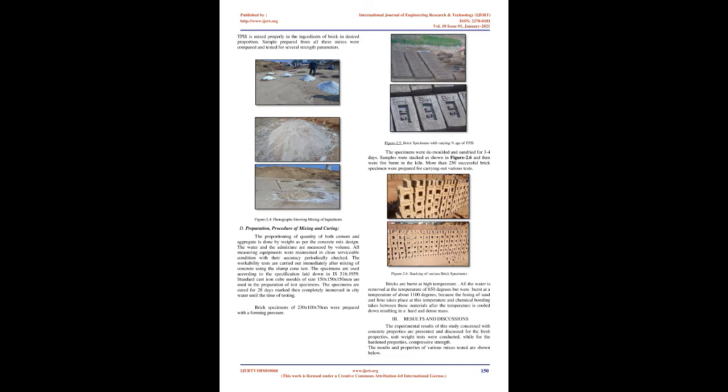Mix constituents. Finally, a mix of concrete of proportion M20, 1:1.85:3.50, was adopted for the present study, table 2.4. The first mix MC is control mix having only cement as binder.